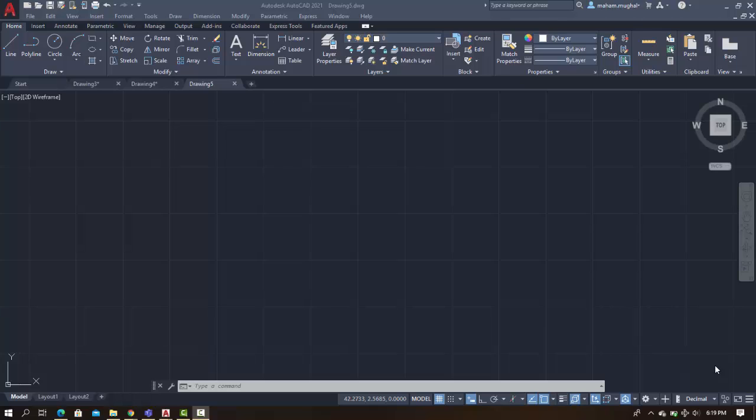When we draw it, the final outcome will represent a 3D object, but the way we have drawn it, it would be in 2D. So let's start. For that, first of all, we'll have to change our drawing style. Usually we use this rectangular interface of AutoCAD, but for isometric we'll change the view, and for changing that view we'll use a command, snap style,